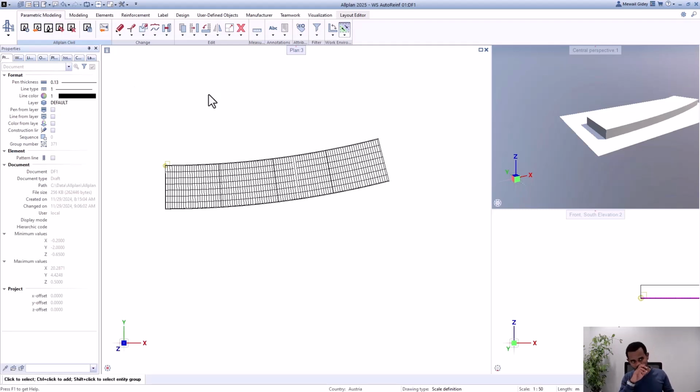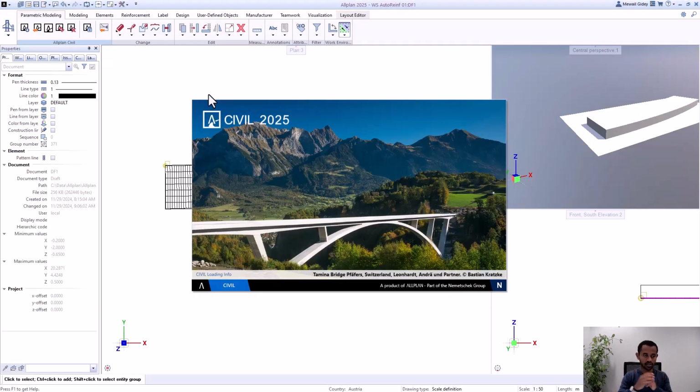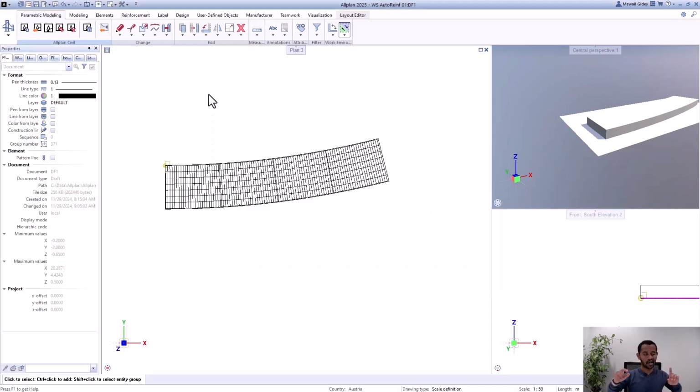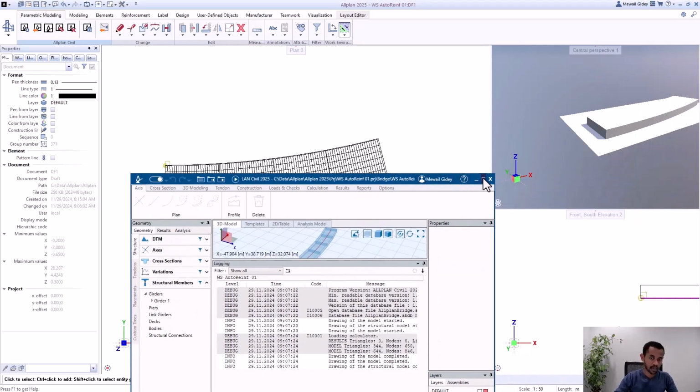What I want to do now is set up first the favorite directly from ALLPLAN Civil when choosing the project. So every time I choose transversal bars, I want to have the hook in, so the hook angle, the lengths and so on, all set up every single time. So I could define it. I could say, okay, transversal or shear or tie bars of hook 90, and every time I have that one, I will just load it.